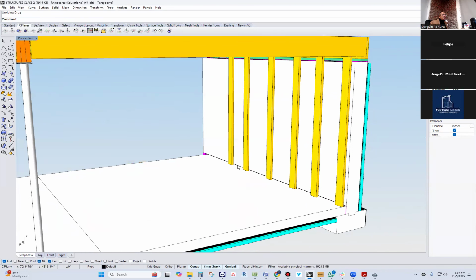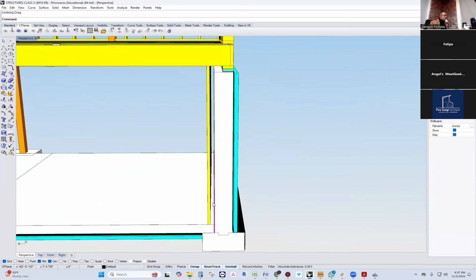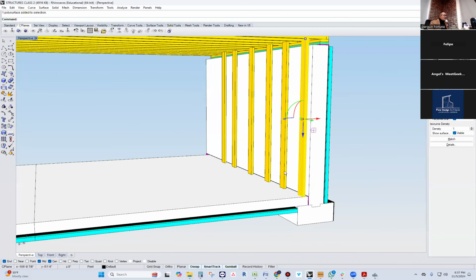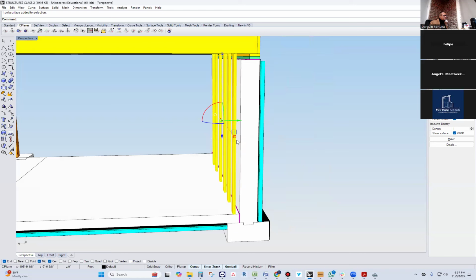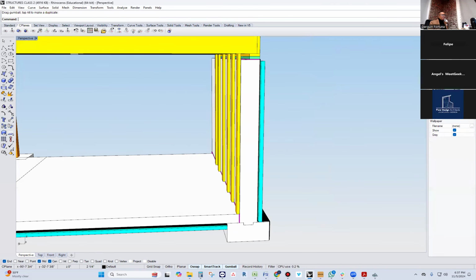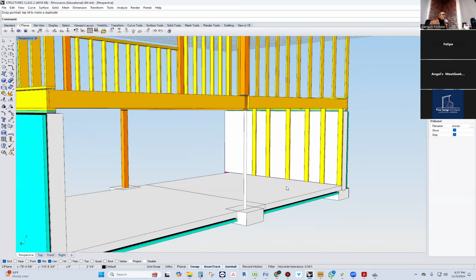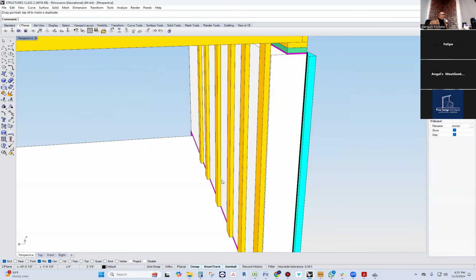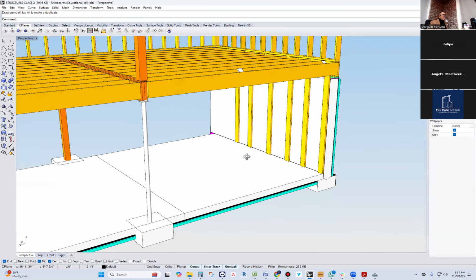We don't typically do that because when you're finishing a basement, you have to get some really interesting R values, and it's very difficult to get the R value if you do them on the flat. By the way, on the flat would actually not be floating. It will literally be right onto your foundation wall. You don't get a whole lot of insulation in there. It's 1.5 inches. That's nearly nothing. So you use that in that case, but you can use it in other scenarios.